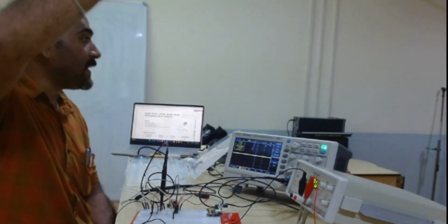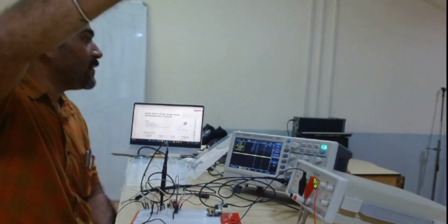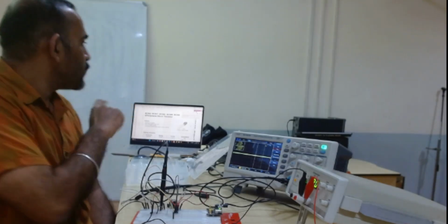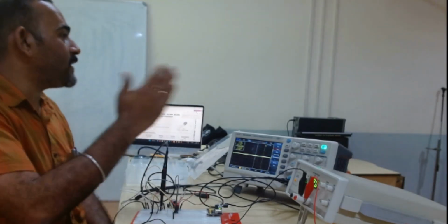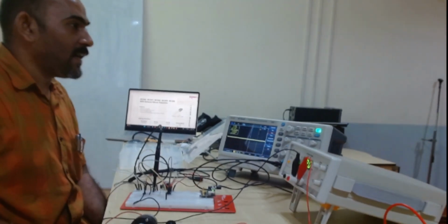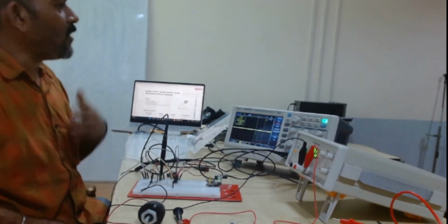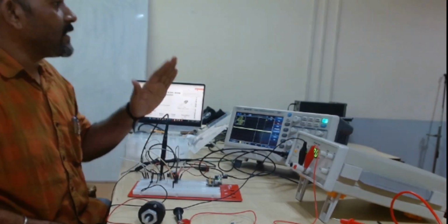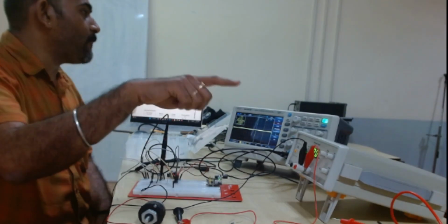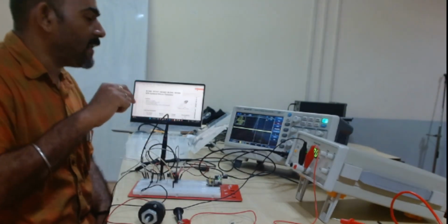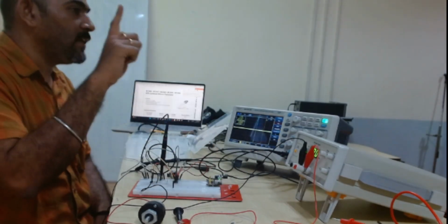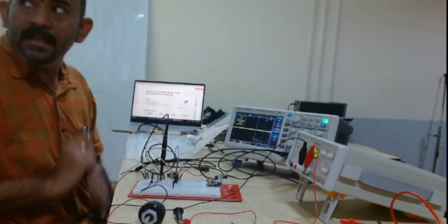Your base and collector are supposed to be reverse biased generally, so current will not flow in that path. So this is a simple way of converting from one voltage domain to another. If you want to drive a higher voltage, you can make use of transistors to do that to a certain extent, as long as you are okay with the connection between 2 voltage supplies. But one thing to notice, the grounds of both the supplies have to be made common. That is a requirement. The 12 volt ground as well as your 5 volt supply ground has to be made common.